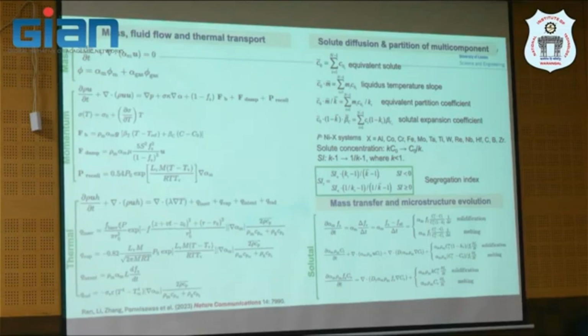So again, this itself is a multi-scale problem. For example, if I'm dealing with a nickel-based superalloy, I would treat this as a pair calculation of nickel and X. X represents all the principal elements used in nickel-based superalloy, depending on which grade you're talking about. But this is up to 15 elements. So this is quite a heavy calculation anyway.